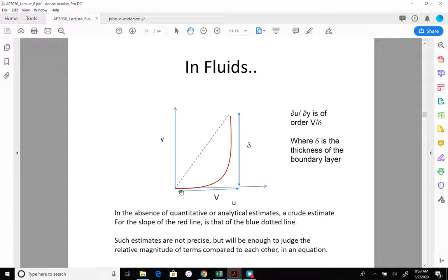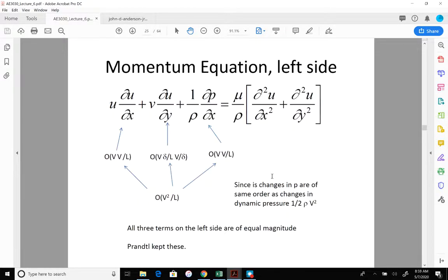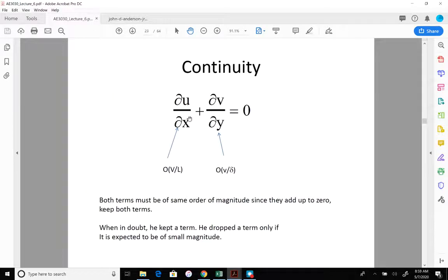then solve the boundary layer equations to get this profile. And very often we are really interested not in the details of the profile, but in some bulk quantities such as the boundary layer thickness, momentum thickness, shape factor, and also the skin friction. So we went over the order of magnitude analysis. We found that conservation of mass stays the same. It does not get dropped.